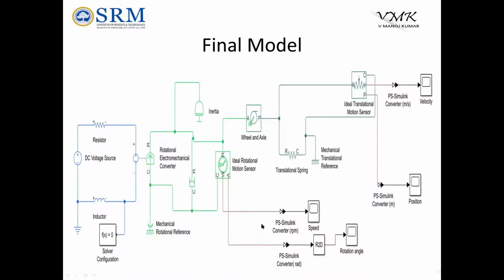Okay, simscape model is different from the simulink model. And now I need to communicate my simscape model with my simulink model. You have already seen in my simulink model what this scope is, is it or not? The scope is a simulink block which I need to communicate with a simscape model, which cannot be done directly. Simscape is a physical model. Simulink is a block model. So I cannot directly connect a physical model with a block model.